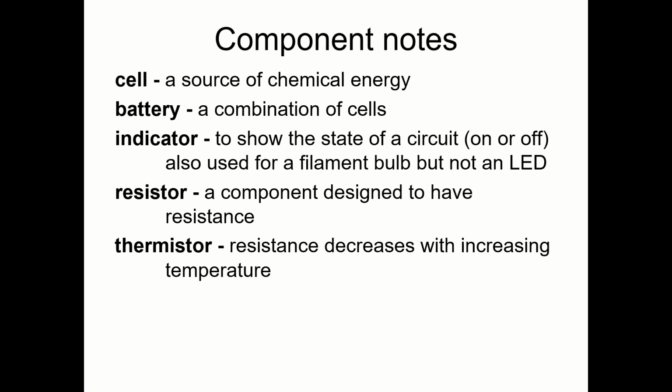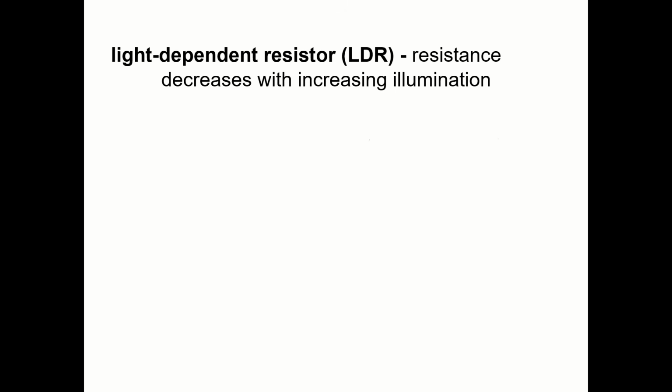Yeah, and thermistors, it's worth emphasizing that the resistance goes down with increasing temperature, which is contrary to pretty much most things that the students will encounter. At GCSE and A-level, I often use the acronyms or phrases TERD and LERD. So TERD for a thermistor, temperature up, resistance down, and LERD for a light-dependent resistor, light up, resistance down. They're quite memorable, those acronyms. Okay. We'll talk about how that works later on. And there's the LDR again, so the resistance goes down as the light goes up.